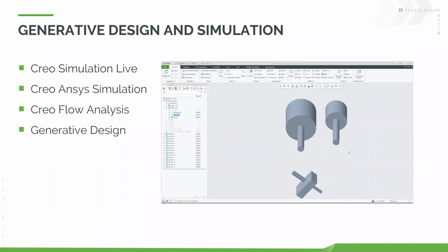And generative design here also got some improvements. We have now the concept of a safety factor to minimize mass at that specified safety factor. You can also now do modal analysis, so maximize a fundamental frequency for a mass volume target, minimize mass for some frequency floor. Around that, we also added in support for ball joint constraints, and now running an initial simulation.